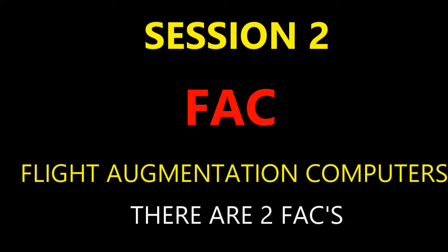And then, of course, in flight, something else you have is the flight weight and center of gravity. Okay, that was an added piece of information for you. But the FAC actually computes the weight of the aircraft. It does this with the air data inertial reference system, your ADIRS, like I've been mentioning, and also with the FMGC and with your FCC parameters, your flap control computer. So again, with speed, weight along with the center of gravity, it's able to calculate that.